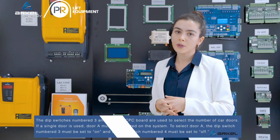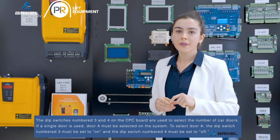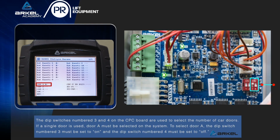The dip switches numbered 3 and 4 on the CPC board are used to select the number of car doors. If a single door is used, door A must be selected on the system. To select door A, the dip switch numbered 3 must be set to on, and the dip switch numbered 4 must be set to off.